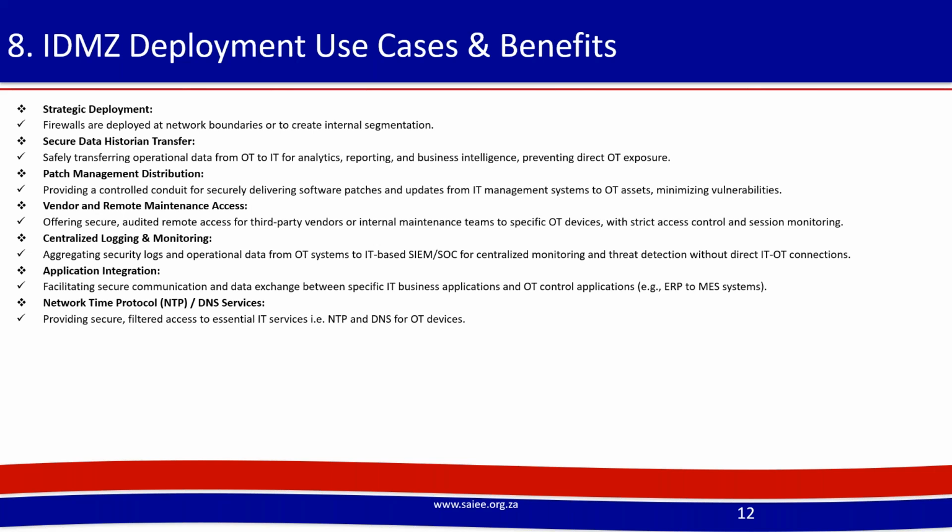The Industrial Demilitarized Zone can also facilitate centralized logging and monitoring, which is important if you want to do this integration. Also to allow your security teams or admins to have visibility on these OT events through a secure channel. If your current control systems are unable to accommodate more signals for security, then you might need a different system such as your SIEM to help with logging security logs.